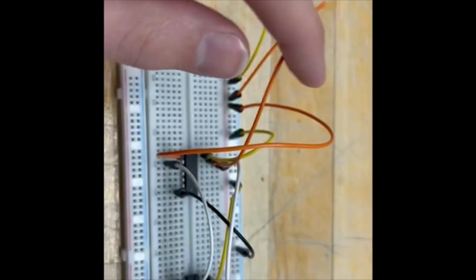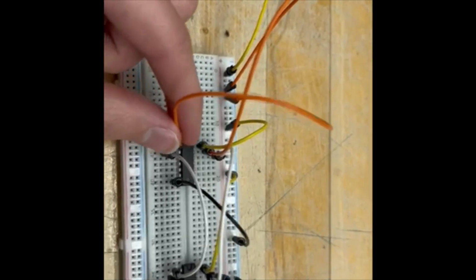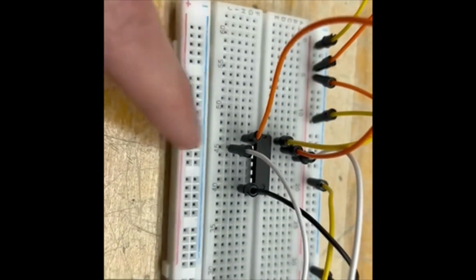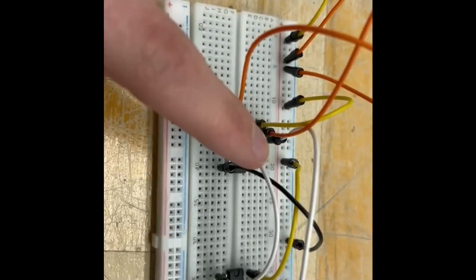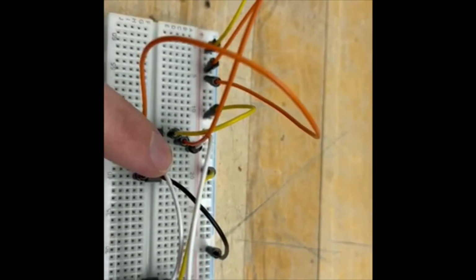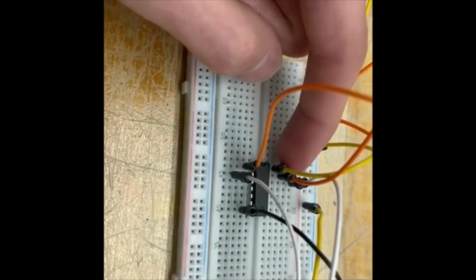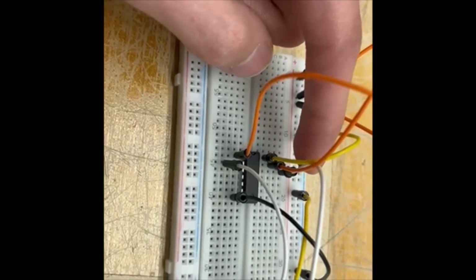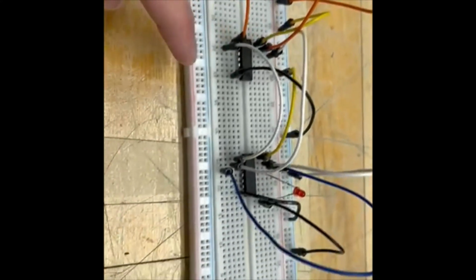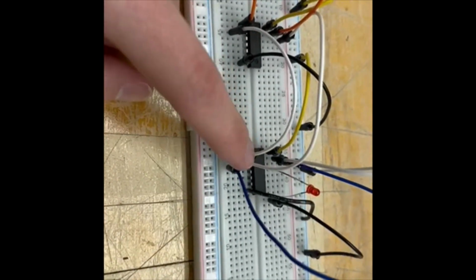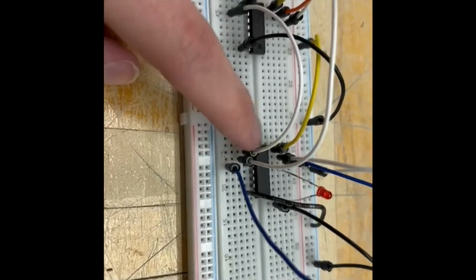So you can see right here, we can say this is z. Z goes into the inverter, and the output is the white. So the white right here is z prime. And the other orange wire goes into here. And the output is this white wire right here, and that is x prime. And both z prime and x prime go into the OR gate, and they are being added to each other.